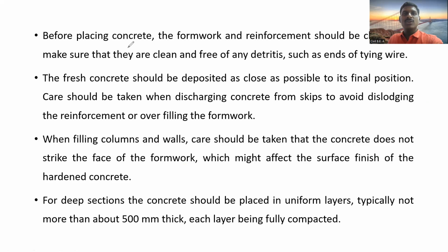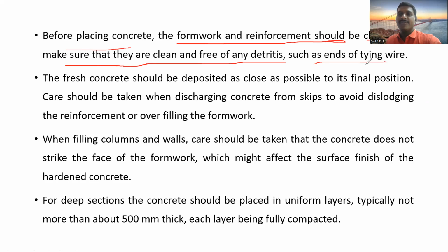Before placing the concrete, the formwork and reinforcement should be checked to make sure they are clean and free of any detritus, such as ends of tying wire.